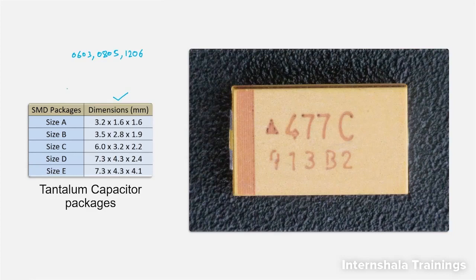Also the price of tantalum capacitor is a very big concern. If a 470 microfarad tantalum capacitor is available in different packages, then based on the price we make the decision which package will be more suitable for the application. In case of tantalum capacitor, the price increases significantly. So always the price is a point of concern when we deal with the tantalum capacitor. And in this image you can see this one is the positive terminal of this capacitor, and this one is the negative terminal of this capacitor.